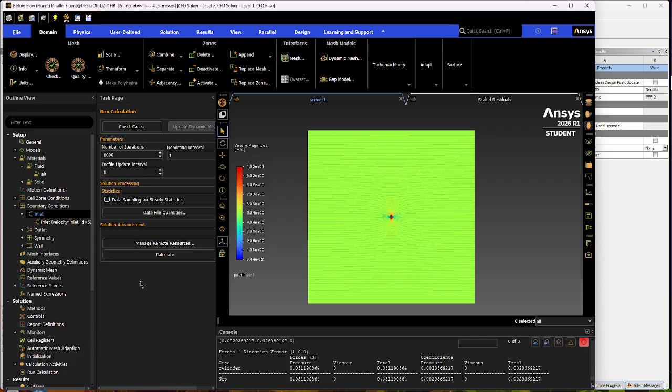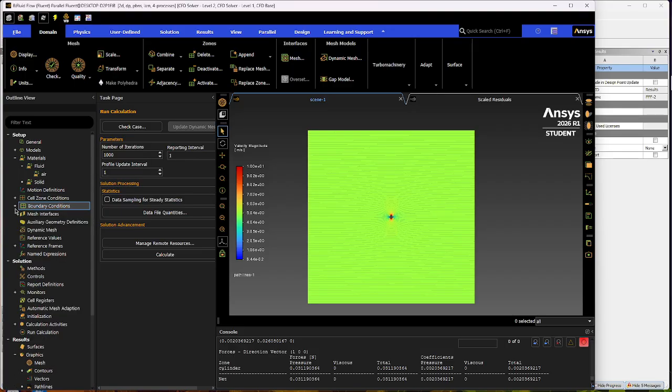So I checked my Reynolds number, and a Reynolds number of a little over 300,000 for the viscous laminar gave me what I needed. And so that's what I'm going to continue doing.